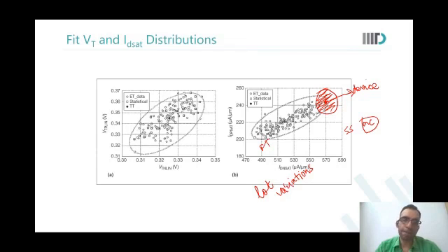No, sir, my question was whether TT should be an averaged-out value of all the corners. Every foundry may have a different way to arrive at TT, Deepank. Some foundry may say, okay, this TT will be my target. Suppose today you want to design in 3 nanometers. The technology is not even there, or even if it is there, it is in a prototype stage. You do not even know what kind of variations will finally happen. So where you will finally place your TT, you have still not figured out, since the final devices or the final materials that you will use in your gate dielectric are not decided.